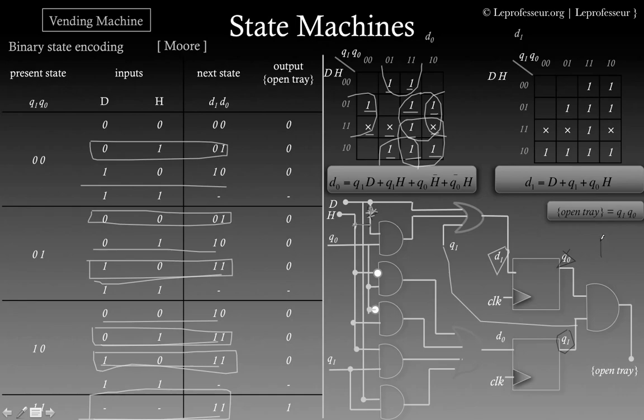We discussed many times, back to back flip-flops or a synchronizing circuit which synchronizes this output, which is the AND operation of state Q1 and Q0, into the receiving clock domain. So be careful with the synchronizing part.